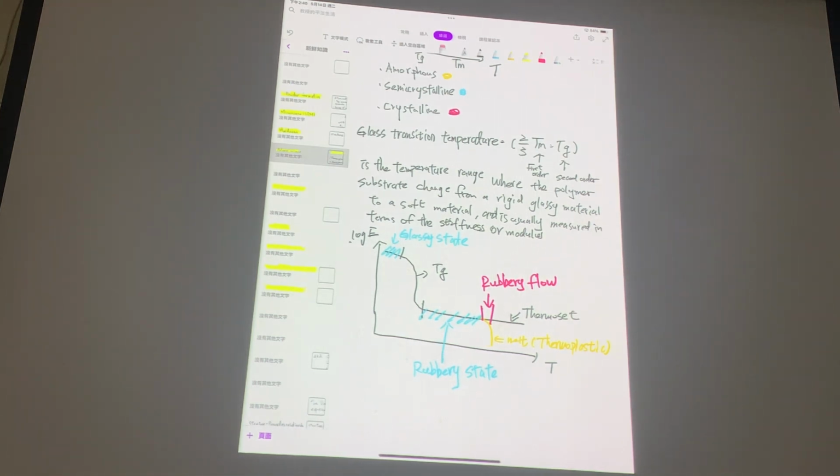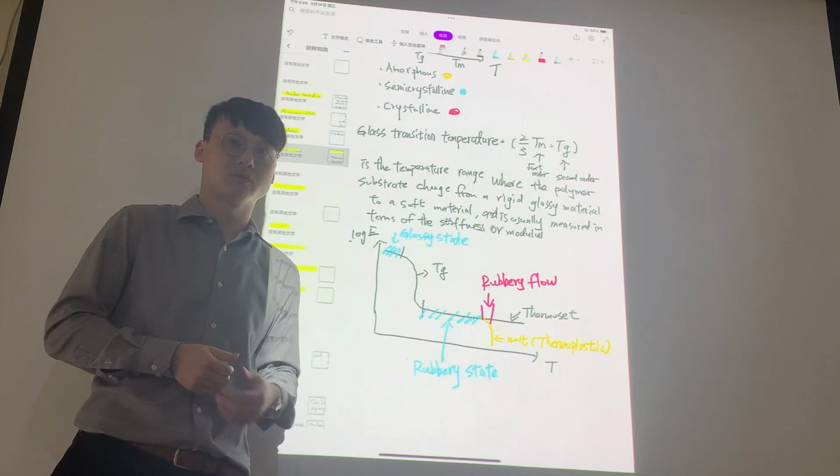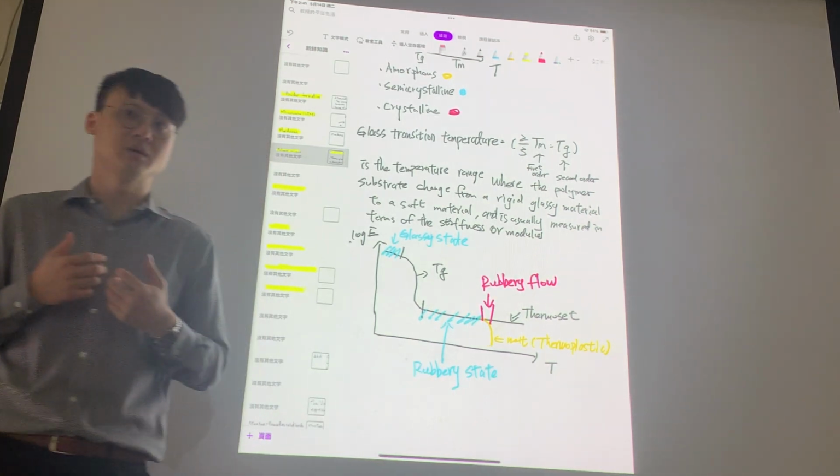The information I want to convey with this slide is that if someone comes to you with a particular polymer material, first you need to ask, is this thermoplastic or thermoset? Second, if it's a thermoplastic, the follow-up question is, is this amorphous or semi-crystalline? Because if it's semi-crystalline, there's a TG point and then there's the melting point. If it's amorphous, there's no melting point. All it does is change the modulus. Okay?